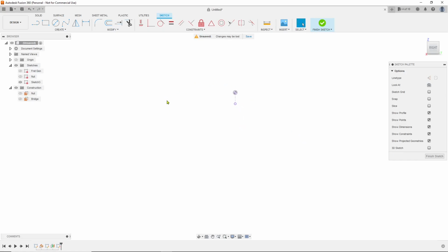Now I'm going to draw a line. This line will be the distance from E string to E string on your bridge, from E string saddle to E string right at the slots. Plus you need some wiggle room on both sides so you can do bends and vibrato and stuff on your notes, pull-offs and stuff without falling off the fretboard. So usually about 0.18 on each side is what I go for, a total of 0.36.